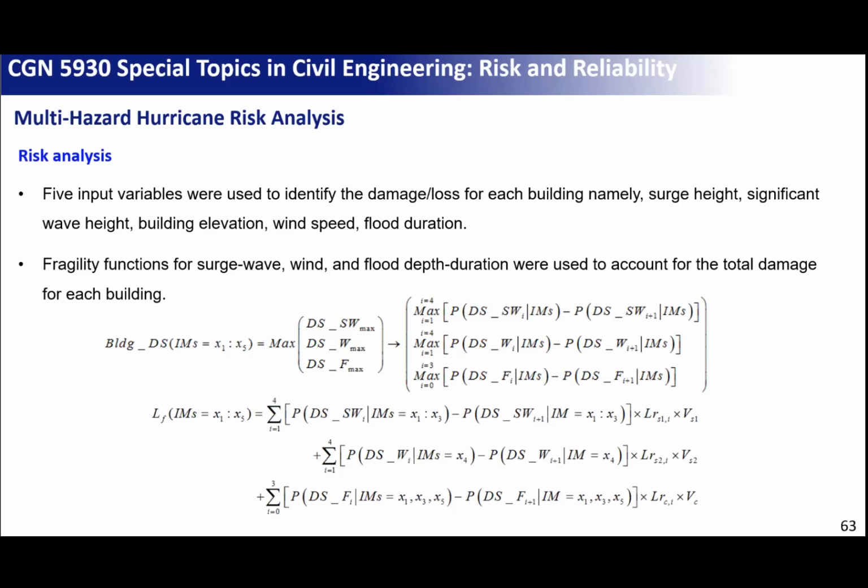But let's assume that a hurricane like Hurricane Michael comes with very high wind speed that can cause very high structural damage, but comes with a very low amount of water and causes damage state 1 to your content, but your building is without a roof. Can you live in your building? So the wind is going to be controlling your damage state. So that's actually what this equation is doing. It tells you what the dominant damage state is for your building.